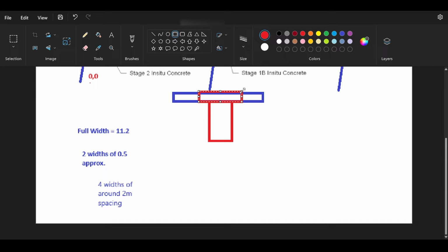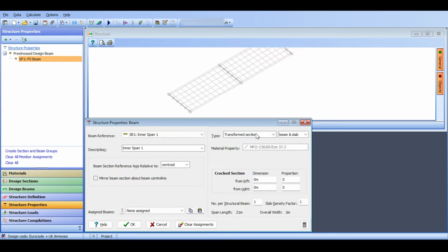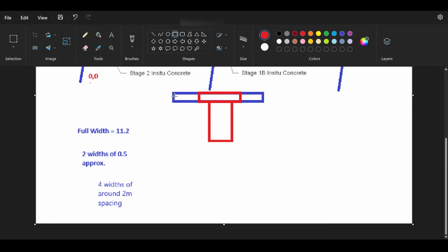Please check out the mechanics of materials books for more details on transformed sections. You will find this in the chapter on bending when it talks about reinforced concrete, allowable stress design or something. So yes, I want it to do this, which means I will select transformed section. If you select gross section, then it will assume that it will not change anything.